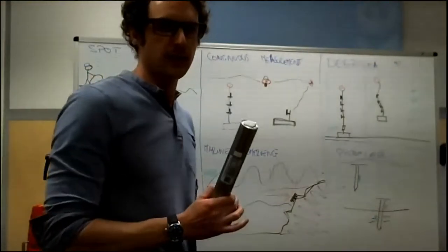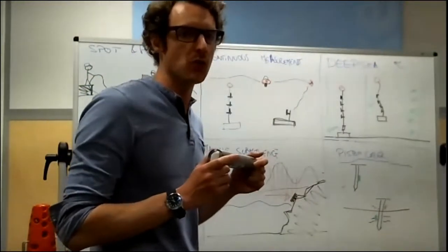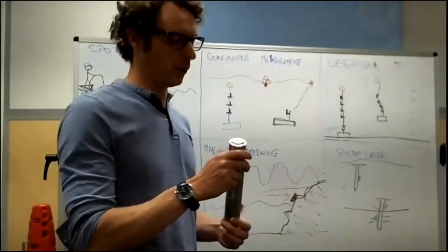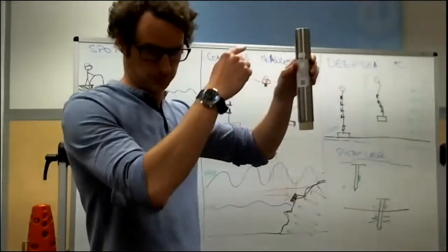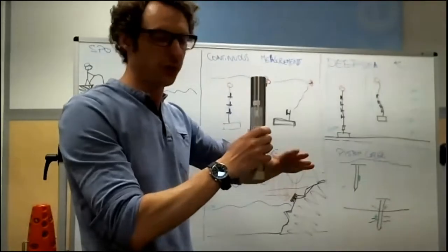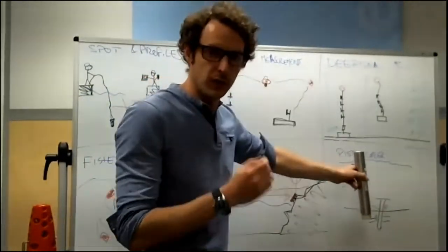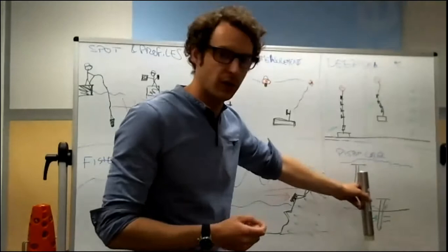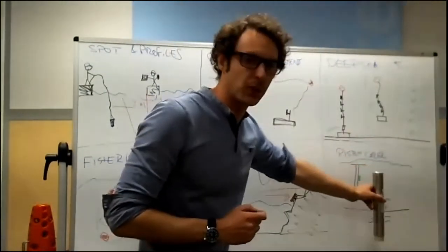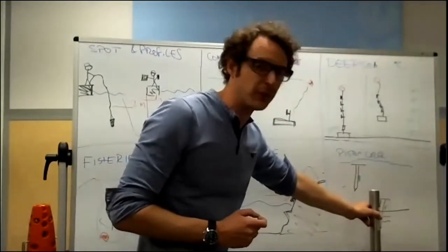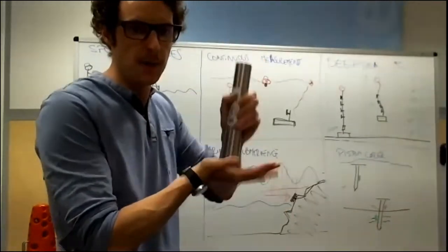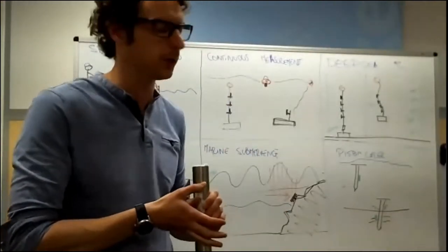This Ysense AD is very specific and dedicated mainly to a single application, which is the piston corer behavior. What it does is it will be deployed, waiting to reach a certain depth that would be close to the sediment area. And once it reaches its depth, it will record at very high speed, 100 Hertz, the acceleration of this piston corer. So this will give information on this key moment, which is the impact and the insertion of this piston corer.